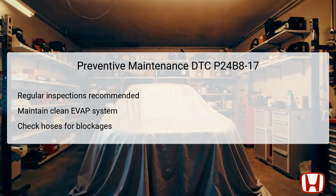Scheduled maintenance provides an opportunity to identify potential issues before they escalate into more serious problems, ultimately extending the lifespan of the vehicle. Keeping the EVAP system clean and free from obstructions is crucial, especially in the drain hoses and canister filter. Regularly checking hoses for blockages or any signs of wear can significantly reduce the likelihood of encountering emissions-related issues. Being proactive in these areas not only helps avoid DTC triggers, but also ensures compliance with environmental regulations.